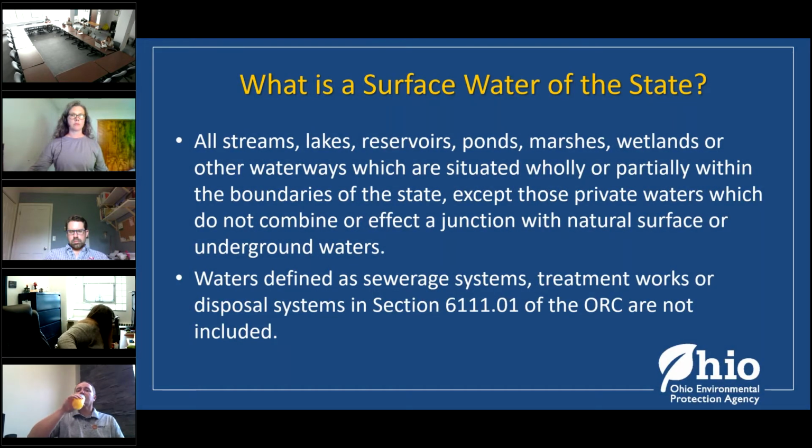There is the condition that when we're doing this maintenance, once you hit final grade, some kind of soil cover is put into place within 7 days of reaching final grade. If this is going to be an area that's going to be disturbed but remain inactive for over 14 days, some kind of cover gets put on that soil within the first 7 of those 14 days.